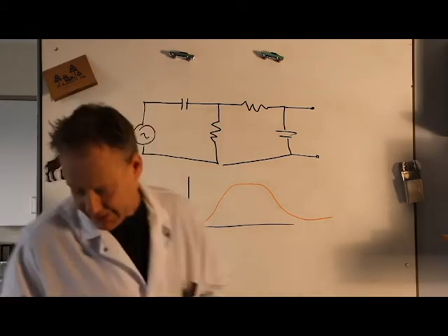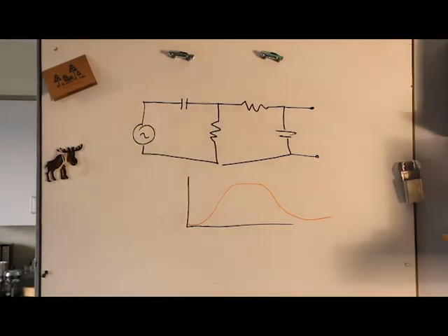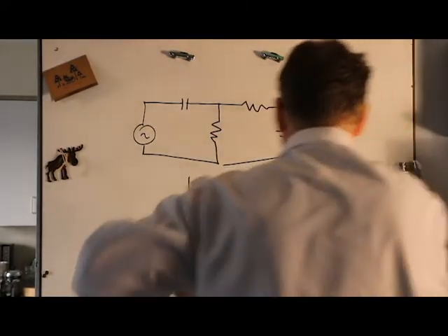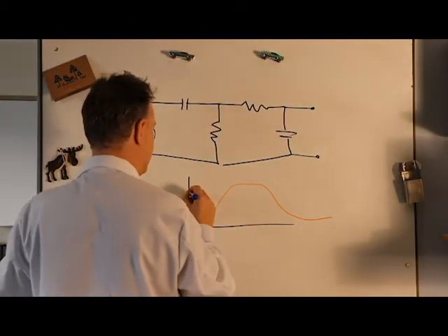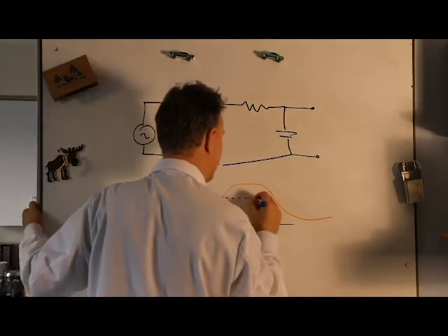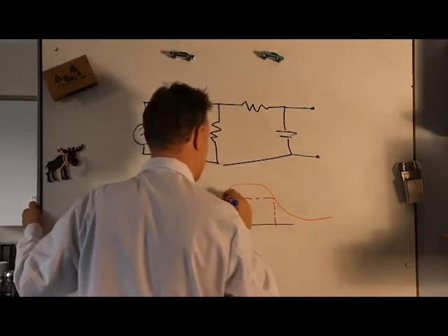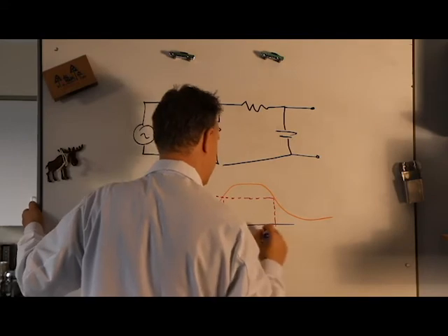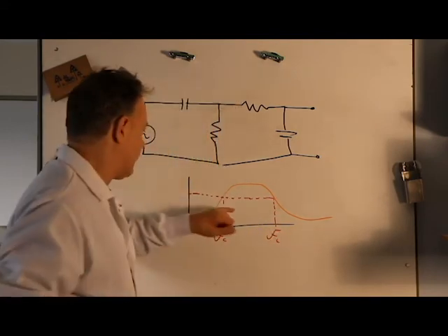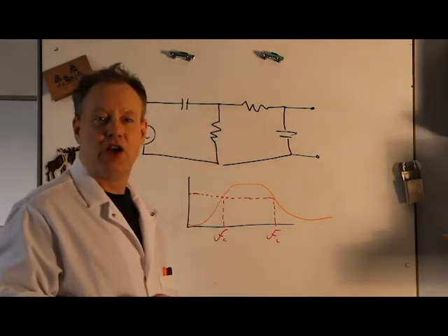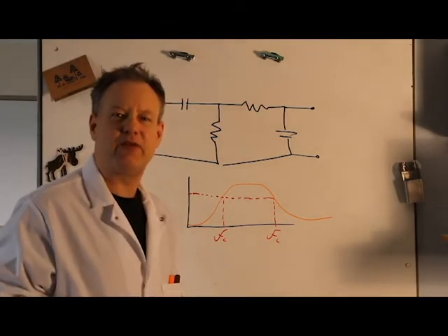As far as the math goes, when we look at their corner frequencies, and we dial in the 0.707, we're right there. That's the corner frequency for the low, and that's the corner frequency for the high. So we can target any specific frequency we want.